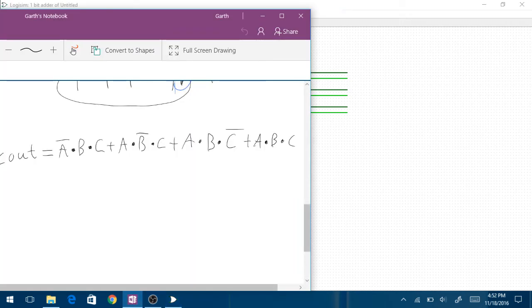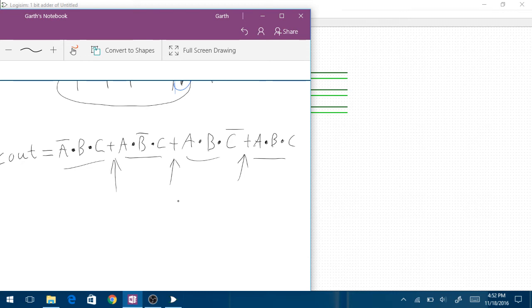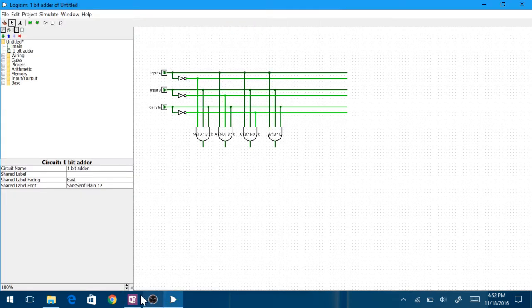We've got more than 3 inputs coming into our OR gate. Notice here that we've got these 4 products, and we're adding each of them together. So this is going to be an OR gate, but it's going to have 4 input lines coming in, one for each of the products. And then the output of that OR gate will be the final output for our whole mathematical expression. That'll be the final answer for our sum of products, and that'll be the final answer for our